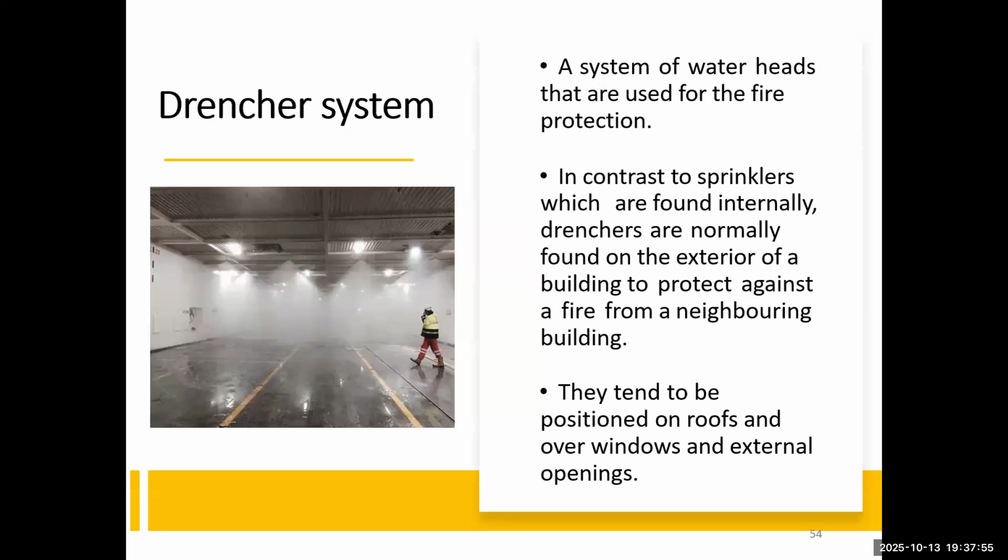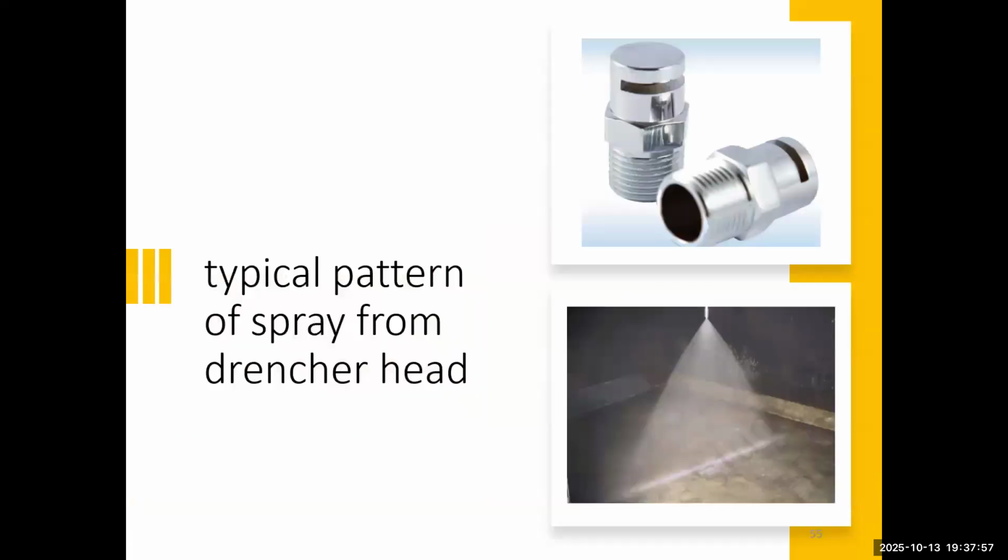And this is a typical pattern of spray from the drencher head. This typical spray pattern is usually installed at every corner of the drencher system to ensure complete coverage of the protected area without gaps.